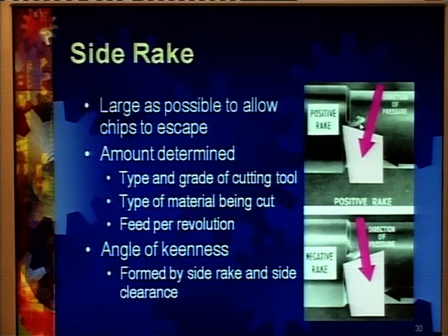But in case we go on increasing this angle, then although the sharpness of the tool is increasing and the flow of chips over this rake face is also made easier, the overall strength or toughness of this edge is going down, and ultimately it may reach a position where the breaking away of the tool may take place.